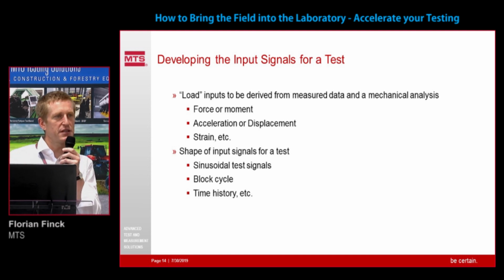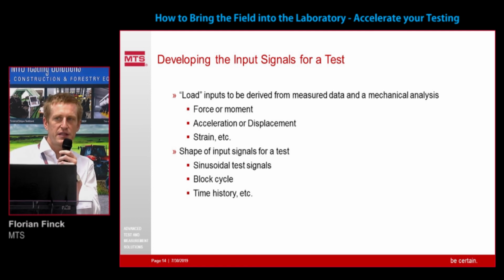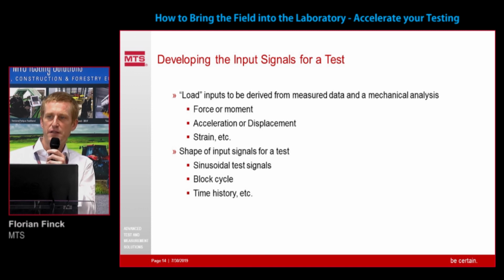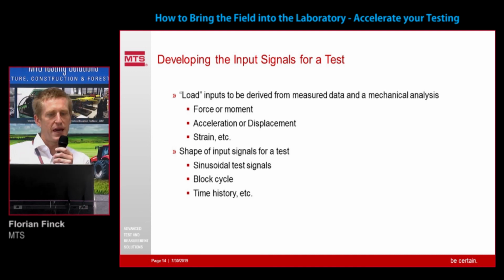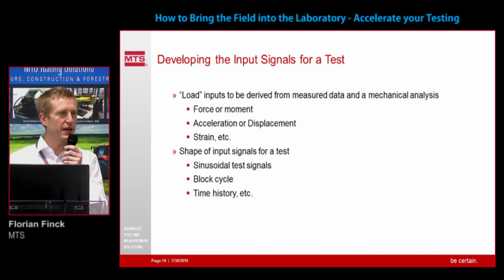So if the setup is very simple, the complexity of the load pattern is rather simple, a sinusoidal test input is reasonable. If you have a dynamic structure, some very complex structure, and a mix of different damaging events that all maybe have a certain time history that is required to replicate these loads, so there's a phase relationship of the loads and the behavior of your specimen, then you will need to go to time histories and the replication of time histories.